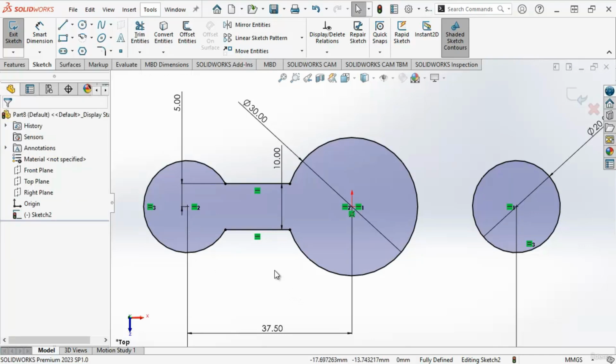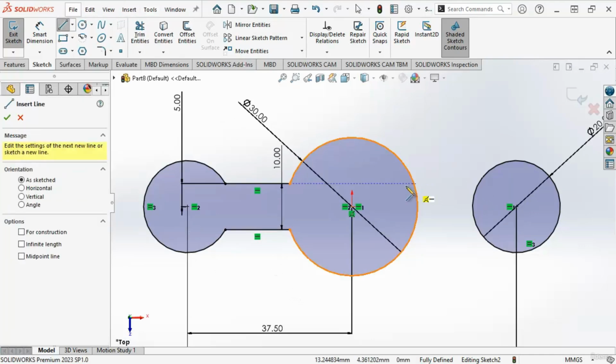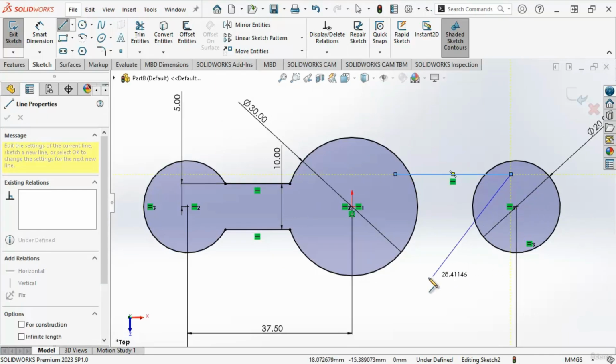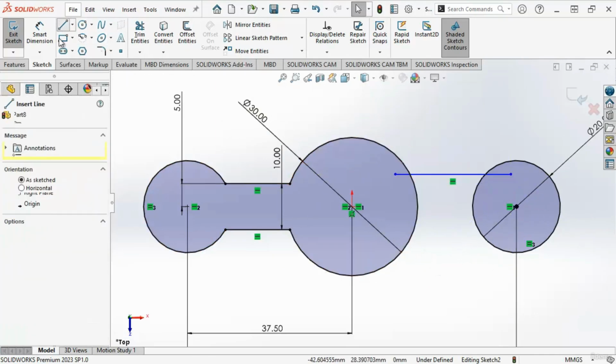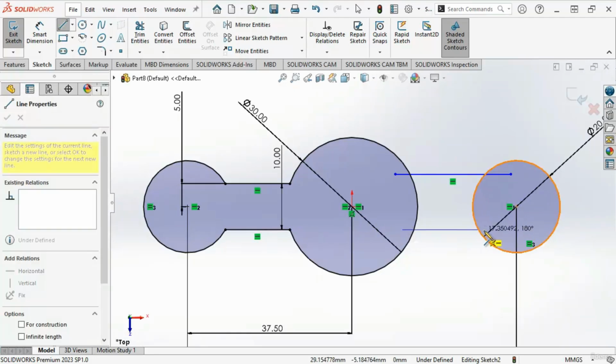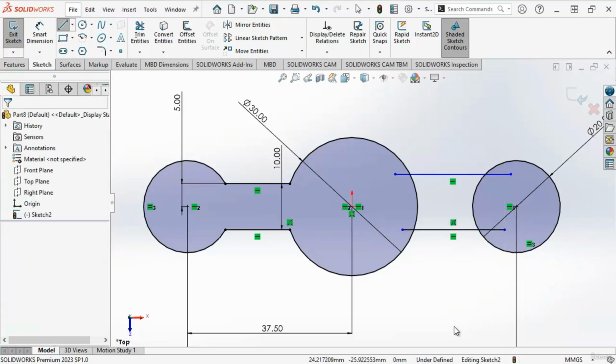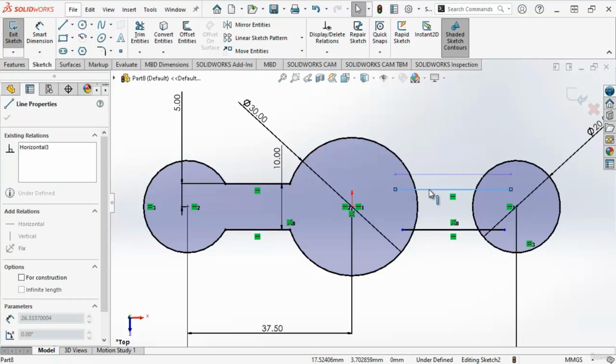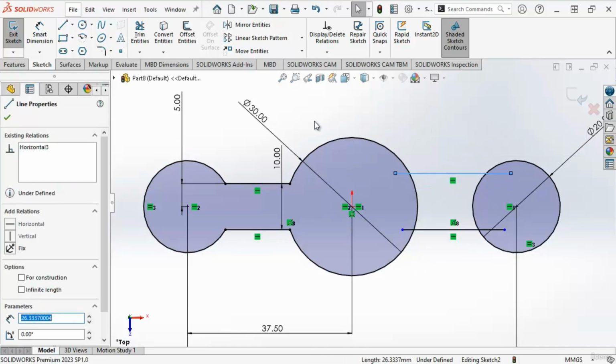You can see. Now, similarly, we can take two lines here, one line here, and another line. If you see, it is tracking. So when it tracks this line, or so to say this point, I'll click and draw a line something like this. What has happened is that this line's position has been taken as this line's position by using this automated constraint called coincident. Similarly, we could have done this for this, but as we have not done it, it doesn't matter.